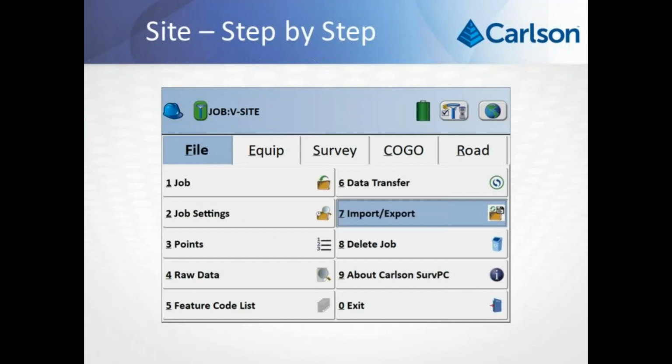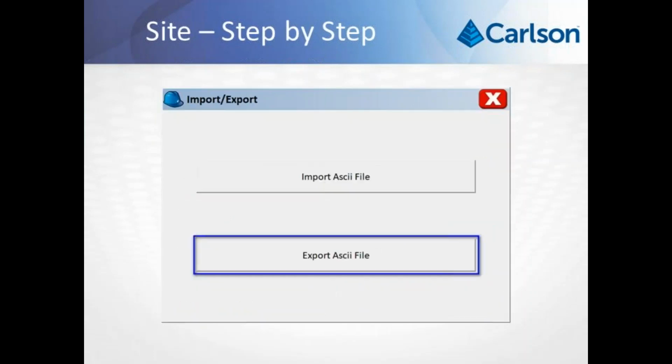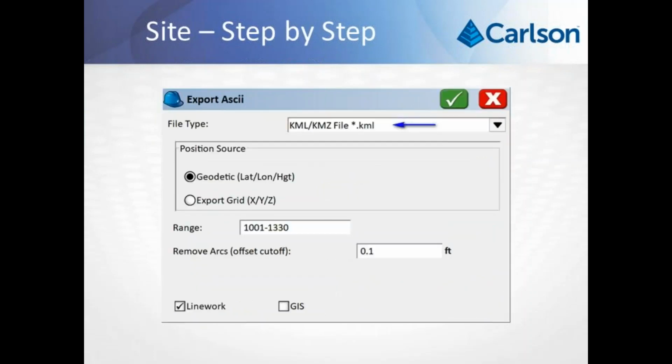And if you want to, you can also go back to the File tab inside of ServPC, choose the Export option, and export out an ASCII file, or even a KML or KMZ file, and send it out to an online application such as Google Earth or ArcGIS Earth from Esri. So that completed, in this case, about a day and a half's worth of data gathering for this whole area.